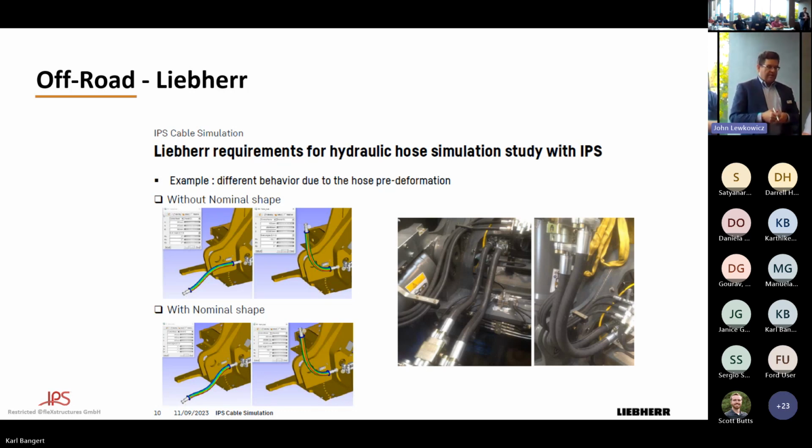Fraunhofer, being the mothership, if you will, has a much bigger lab, which if you get a chance to see it is impressive, to measure hydraulic hoses, I think up to 300 millimeters diameter, and they're going to go up to 500 bar pressure or something. We're doing in the hundreds now, but going into the thousands. It's amazing, together with a heat chamber and a cool chamber as well. So you get those different types of operating conditions.